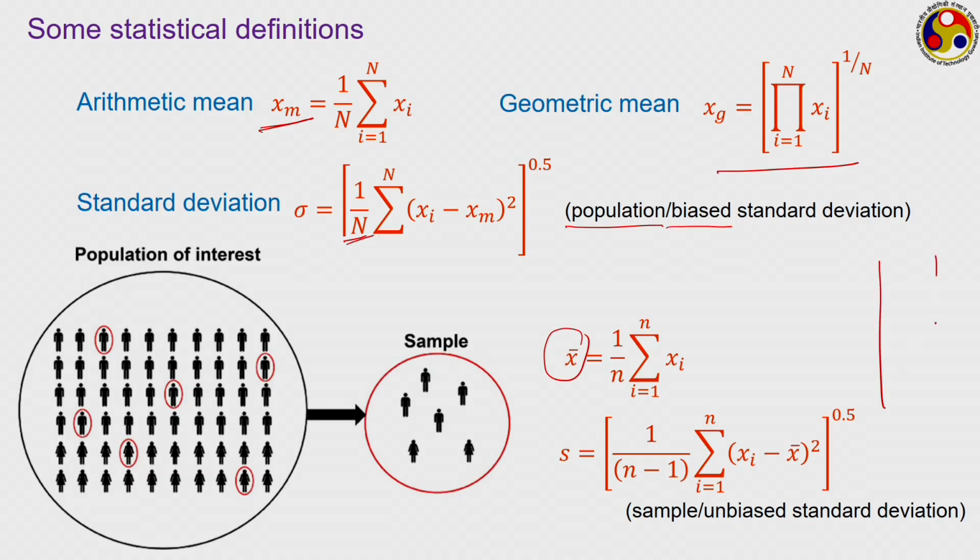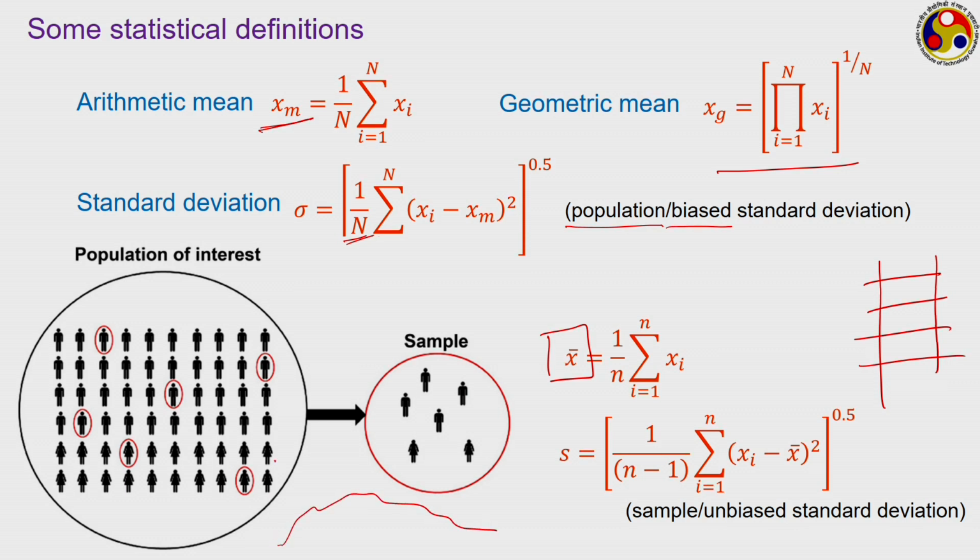So, instead of measuring so much data, we decide to measure just 10 or 12 pressure values, one after every second. So, we have 12 values of pressure listed in a table like this, with a pressure value at every point. Now, the value of this x bar that we are going to get depends upon which values we pick. Suppose your pressure is varying in this way, with time on this axis and pressure on this axis. Instead of taking such a continuous measurement, which would lead to the population and an infinite data set, we are taking samples at certain points.